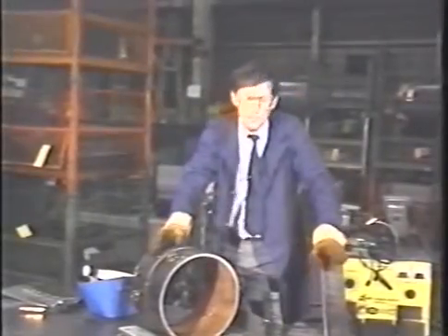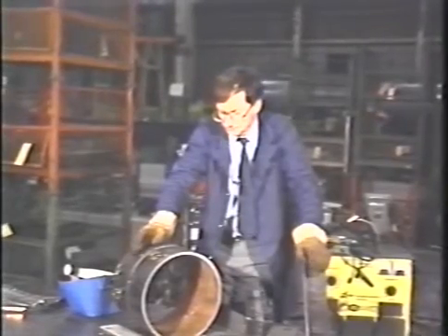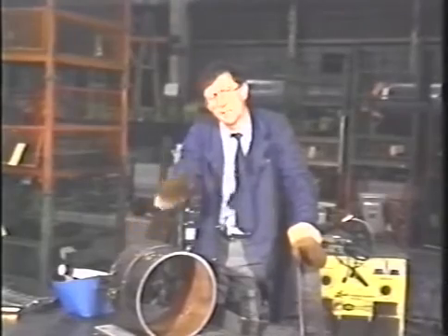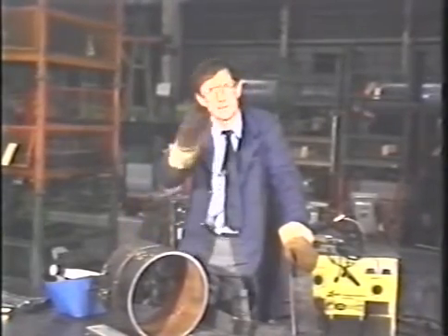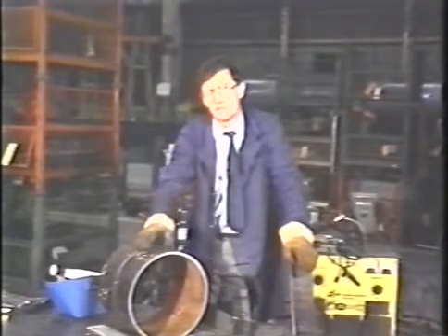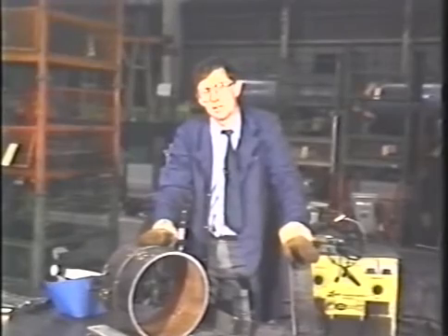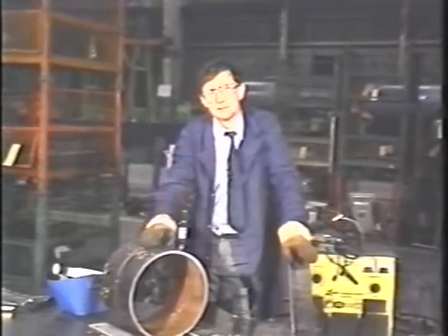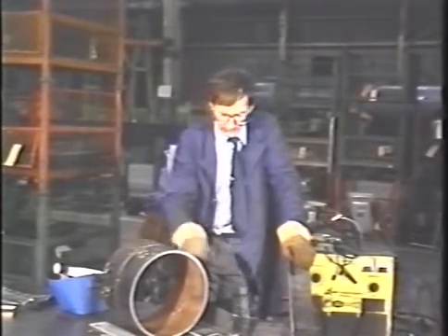So far we've talked about the basic requirements for short circuiting. Voltage around 17, 18, wire feed around the 10, 11 o'clock position, or you could even start it off in the middle, as long as you're in the range. Let's look at some real applications with one objective in mind. We don't want spatter, and we want to do all these applications on one simple setting.